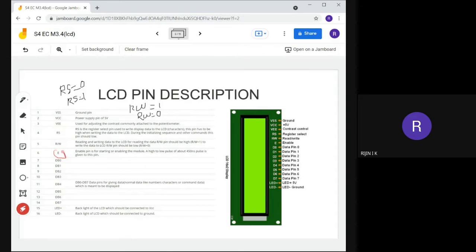Then one more pin is the enable pin, which is used for enabling the LCD. For performing that operation, we need to send a high to low pulse. High to low pulse means first we set the E pin equal to 1, then after a particular delay, we set E equal to 0. That means high to low. I forgot to tell you that the enable pin is also there.